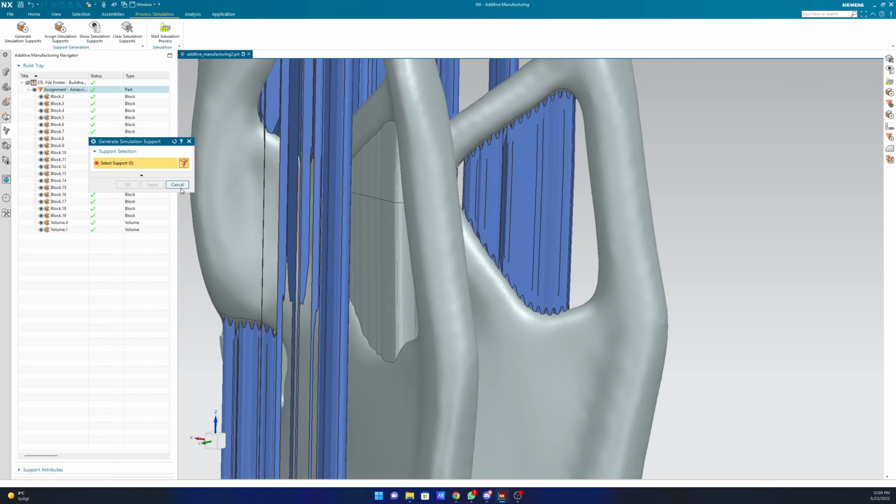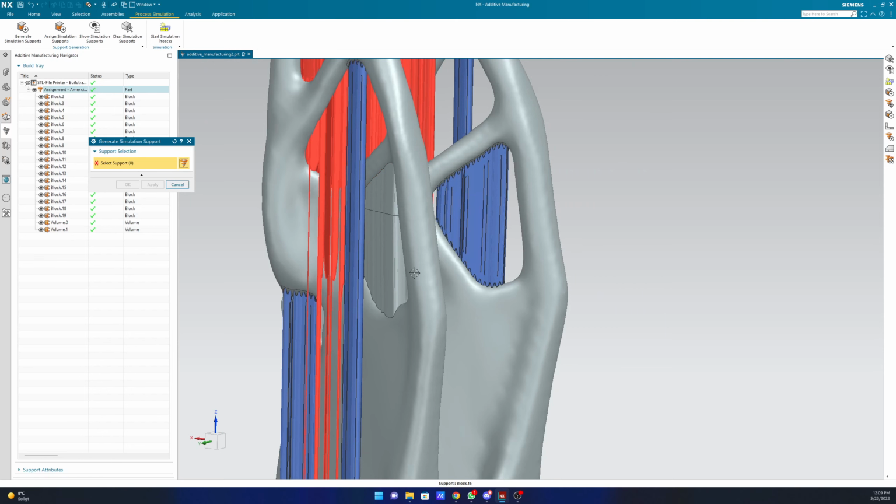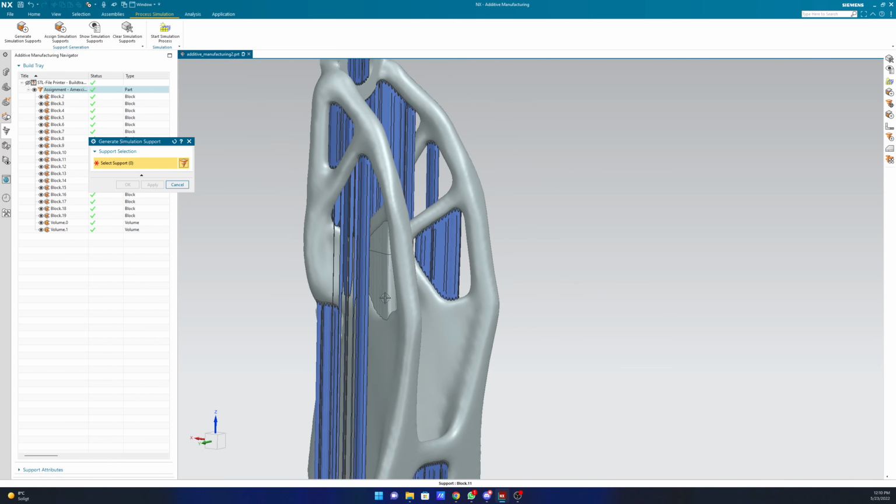So, what was the error initially? What was the software telling us about the error? When the support is on a very slanting surface, it gives you an error. It cannot compute that kind of simulated supports. If the base is approximately flat, it can simulate those.